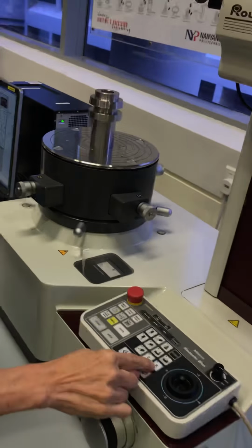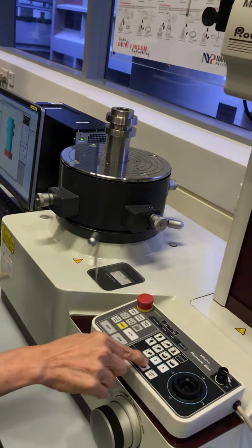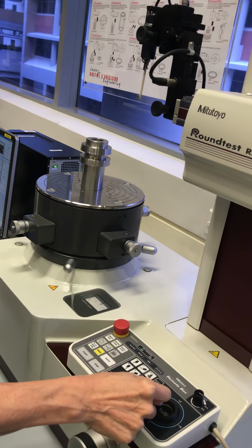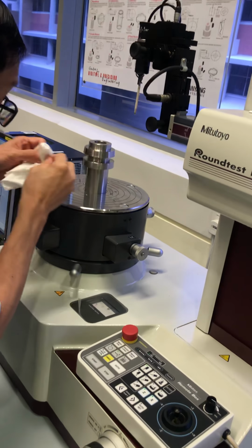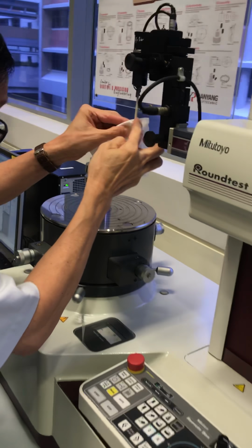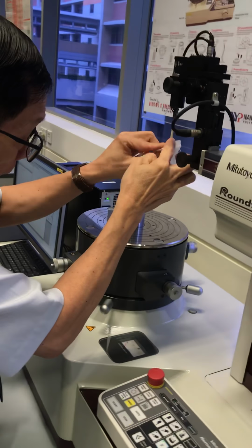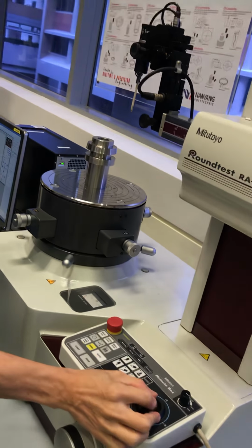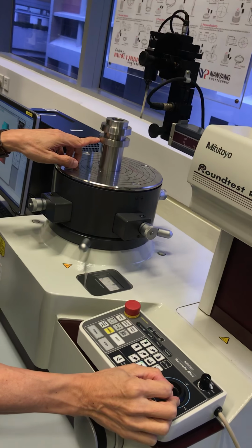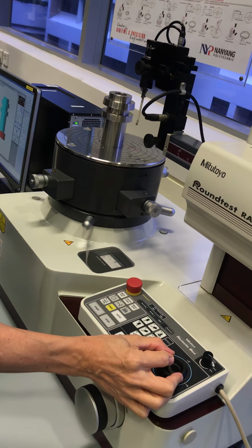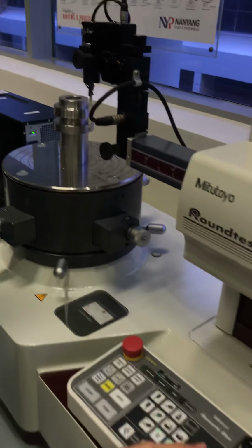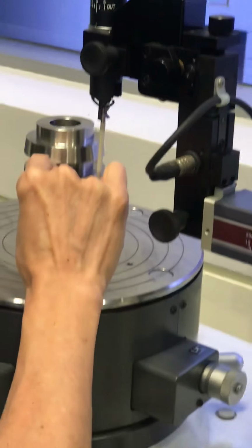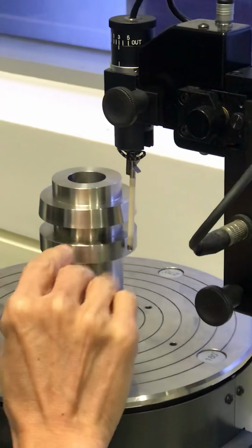You turn on the X and the Z button here. Then you can move along the Z and the X. And then the tip here, if it's dirty, you clean it first. Hold it here for support, and then you just clean it. Is this clear? Then you can bring it closer to diameter A. Diameter A is this diameter A, about 1 mm away, and in the center plane of this height, in the center of this height.